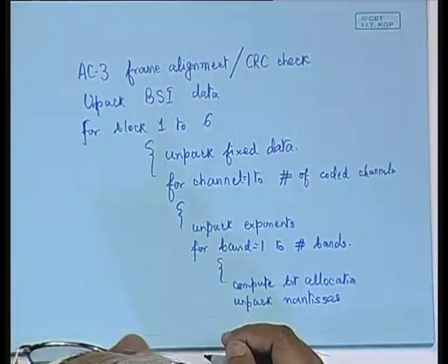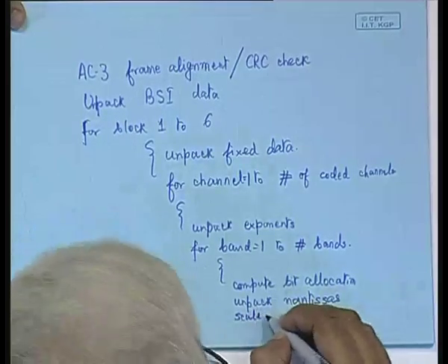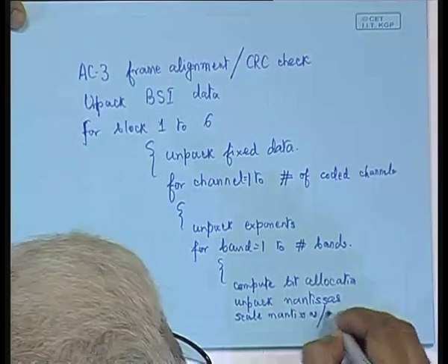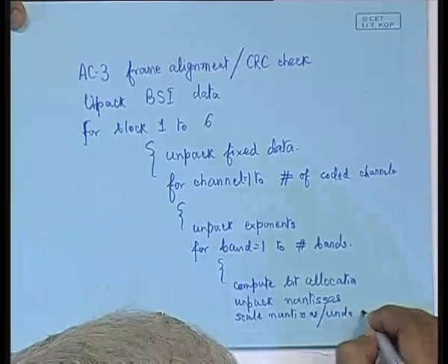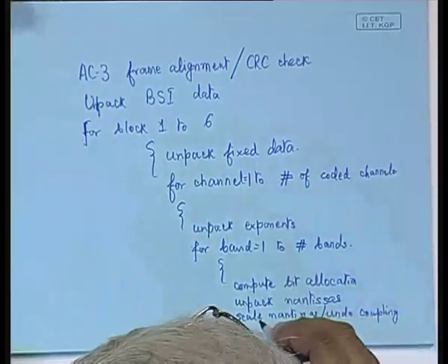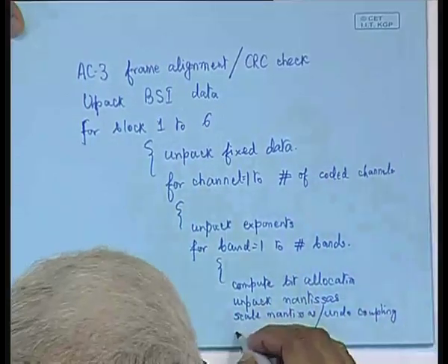Then if you have done high frequency coupling as I have mentioned a little while back, you have to undo that coupling. So, after unpacking you have to scale the mantissas, or undo the coupling, and then you have to denormalize the mantissas.